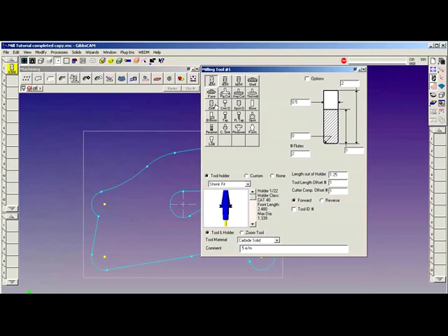All right, back to the tool matrix. As I mentioned, these are pretty much segregated by category. Rough end mill and finish end mill use the same definition parameters. Ball end mill, slightly different. You've got overall length, diameter. We lose the dialog for the corner radius because a ball end mill is assumed to be a full radius cutter. Number of flutes, and once again, length of engagement.